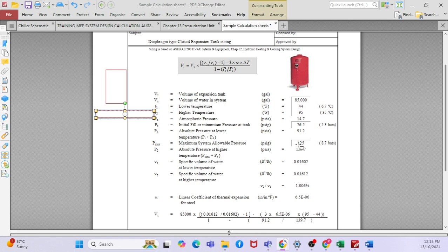Normally you will operate your system at 1.5 times; you have heard about PN10 or PN16 or PN25. So that is the maximum pressure. PN10, PN16 or PN25 will vary depending upon where you locate your expansion vessel. In some projects you might have seen the expansion vessel located on top of the system, while your chilled water plant is in the basement, because the static head also affects your expansion vessel.